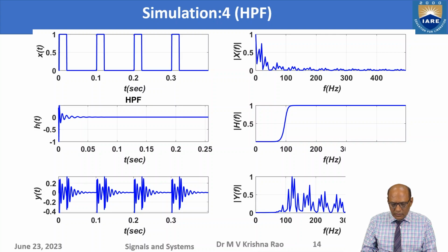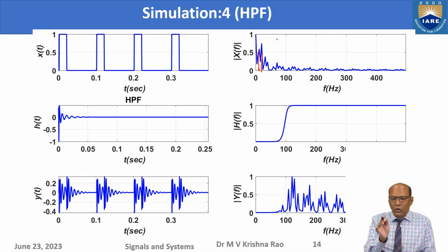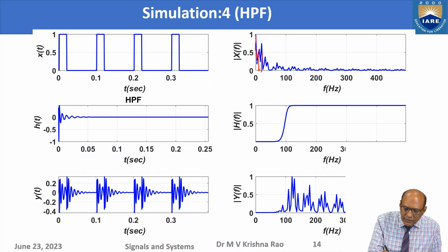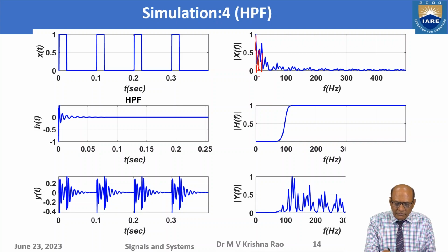Periodic narrow pulse width. The important thing here is that because of periodicity there is a line spectrum. There is one line developing here. The spectrum main lobe is splitting as a line spectrum. And the split is not perfect because the cycles are not infinite.